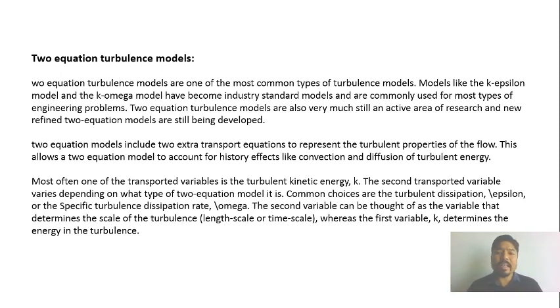If you are going to analyze the turbulent nature of the fluid flow in that particular region, you are of course going to solve that particular problem. Okay, this allows the two equation models to account for history effects like convection and diffusion of turbulent kinetic energy. If I take an example of the K epsilon equation, one of the very important equations which is used to solve a kind of turbulent problem. Okay, the minor turbulent problems we can solve by using this K epsilon equation very easily.